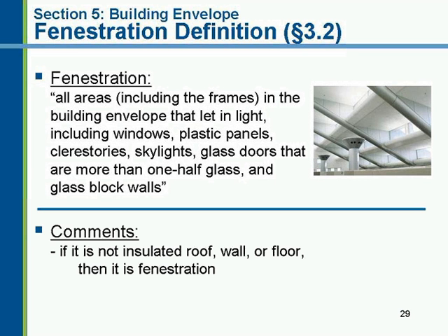And again, with spandrel glass, it doesn't matter what the exterior surface material is. If it's got insulation behind it, then that's more considered a wall. But if it does not have insulation behind it, then it would be fenestration.